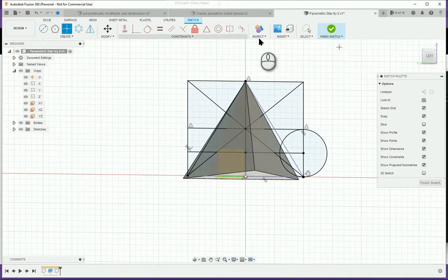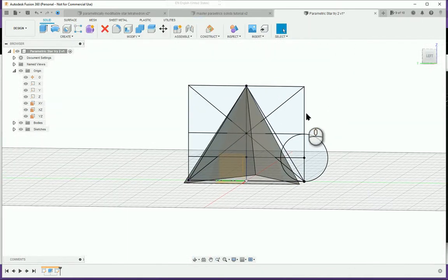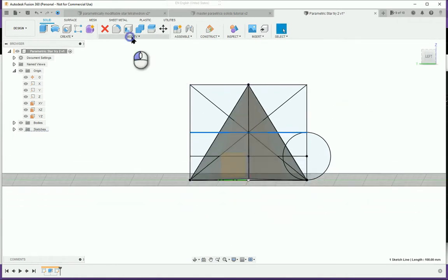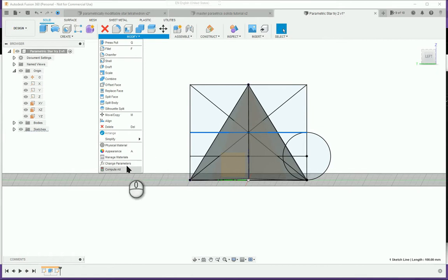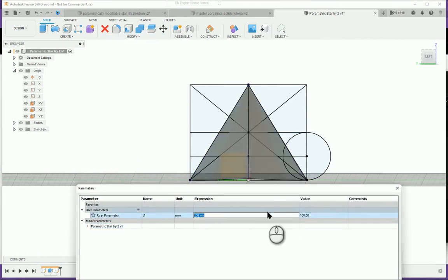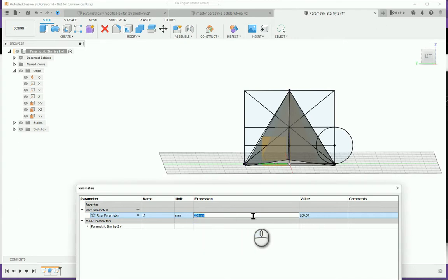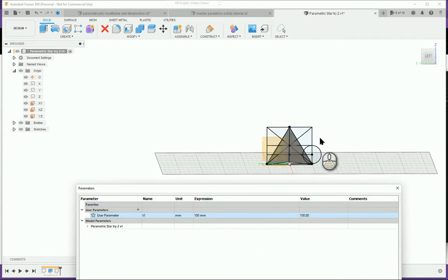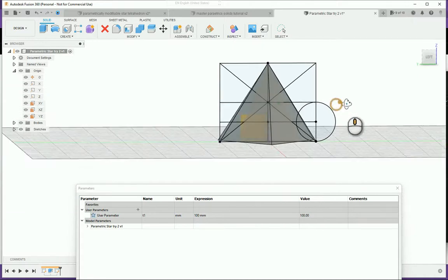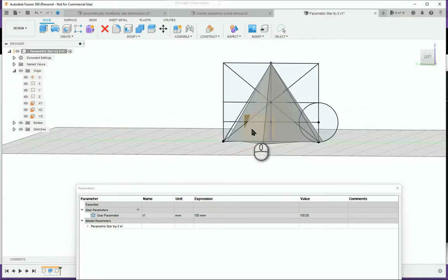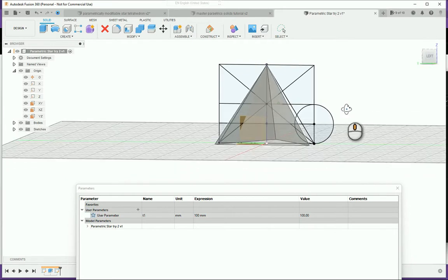Okay. I'm going to finish sketch just to really check, make sure this is secure. You don't want to move it around. You want everything constrained, I suppose, properly. So this is how you see it. Like none of it moves around, but I can go into the parameters and change the parameters so it's not entirely stuck. I'm going to change it back to 100. So that sketch and that little platonic solid is now parametrically driven.